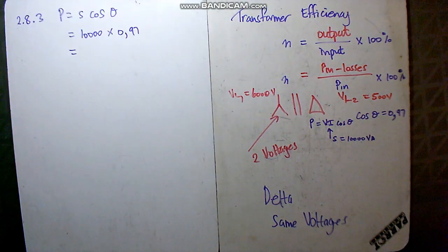You will note we calculated the true power up above. So the same, use your formula, power equals S cos theta. The S was 10,000 times the power factor.